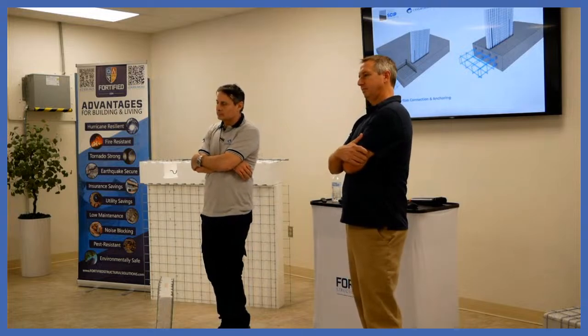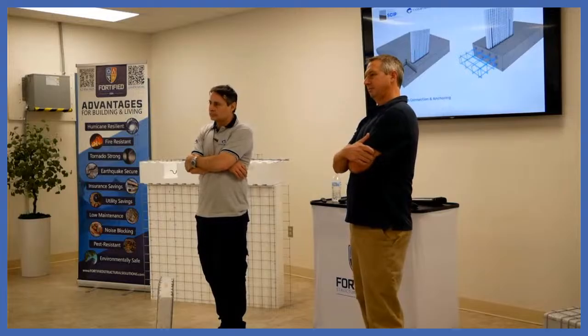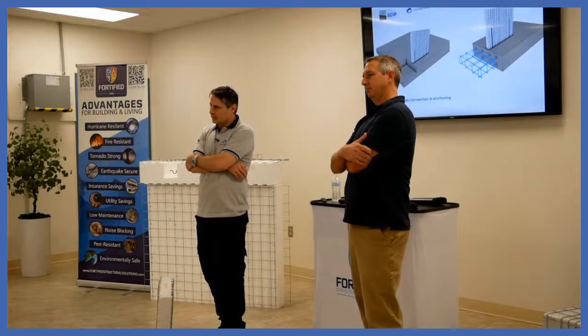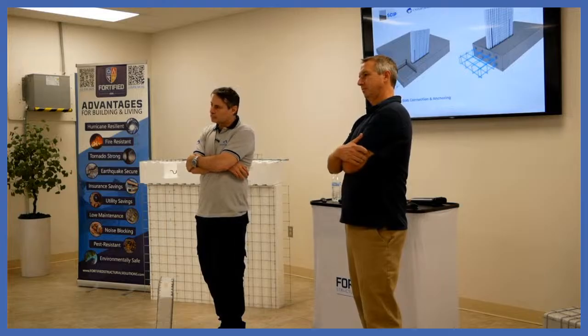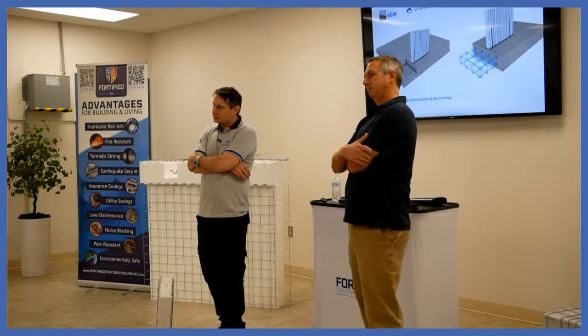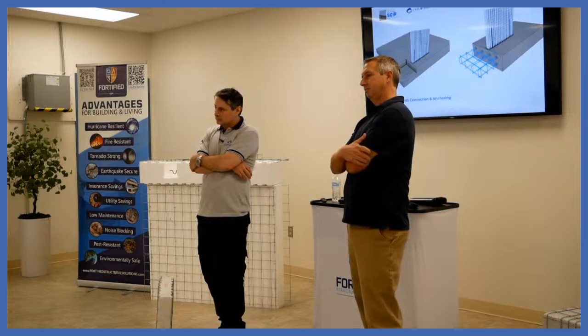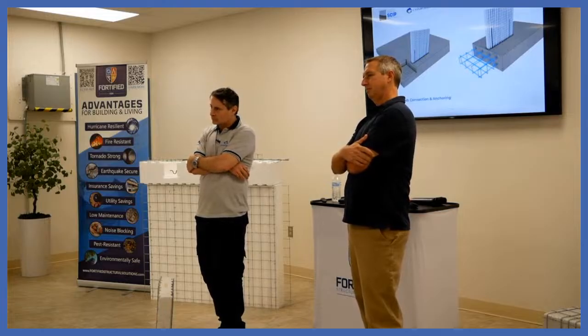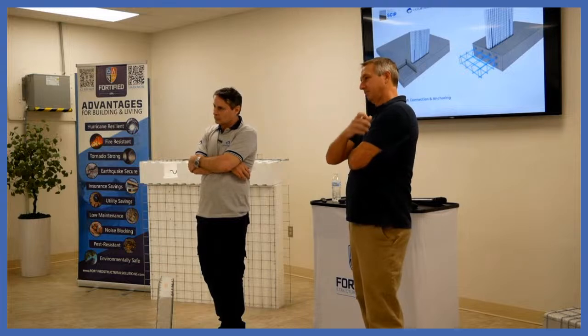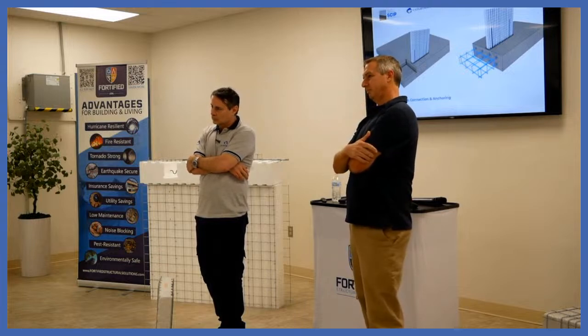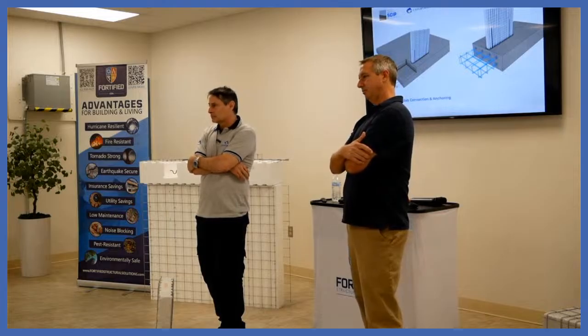I just want to make sure, because this is how I thought of it: if I just do the old numbers, as far as a thickness of a beam, and I shoot that up with the type of mix we're coming up with, it should always be good, right? I mean, if an LVL would do it, this would do it. And if we don't have time to run the numbers, we put a 60-minute skip in with number 4 GFRP bar, 4 rods, bottom. We shoot that with our pick. You've got at least 10 times the strength of an LVL.